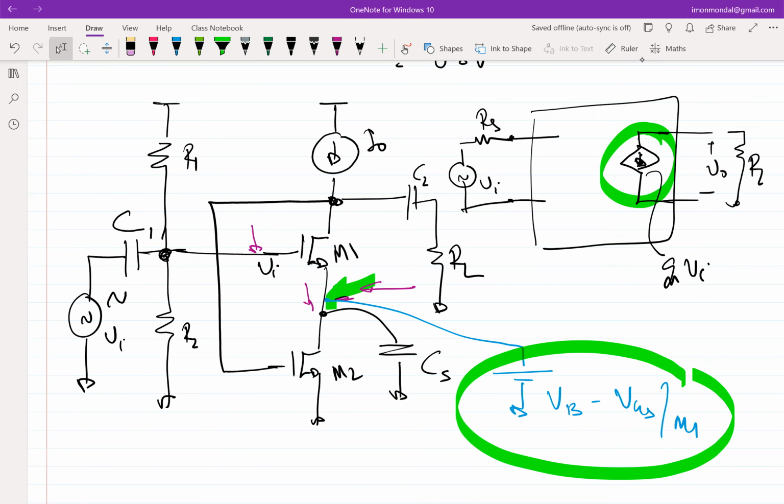You can argue it philosophically. What is the role of negative feedback? The role of negative feedback is to ensure that whatever change is there in the ambient condition should not affect the functioning of the circuit. When I say it should not affect the functioning of the circuit, what I essentially mean is that it should not affect the biasing condition of the circuit. Now, what is a resistance? How do you figure out a resistance? There are two ways.